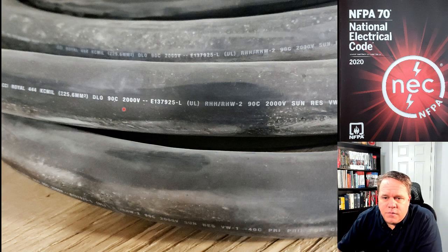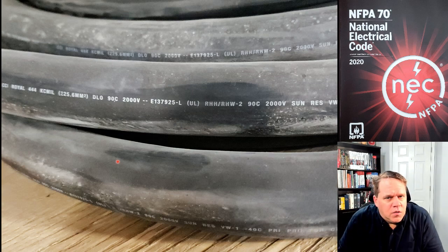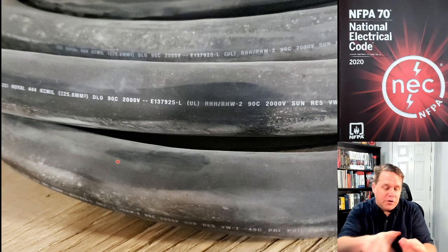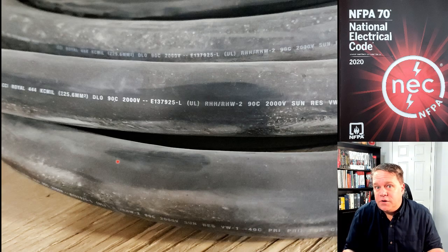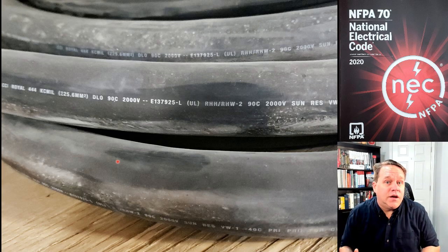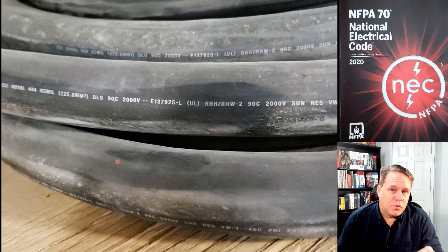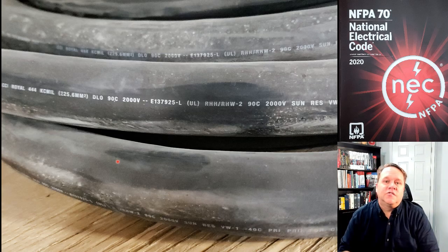What do we have here? Ooh, looks like we have some DLO cable. I don't remember seeing DLO in table 310.4, and that's because it's not there. Okay, what do I do if I have a conductor that's not in table 310.4? Well, the answer is simple. You don't install it. You can't just take a piece of copper, wrap some sort of non-conductive material around it and think that the code recognizes it. That's not the case. Only the conductors that are recognized in 310.4 can be used. So this is DLO. Can't install it.